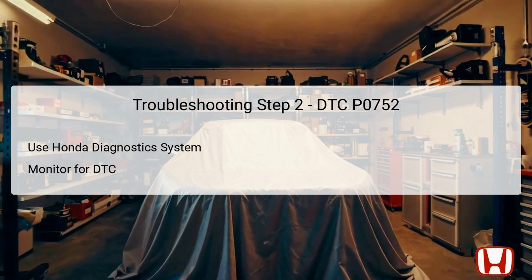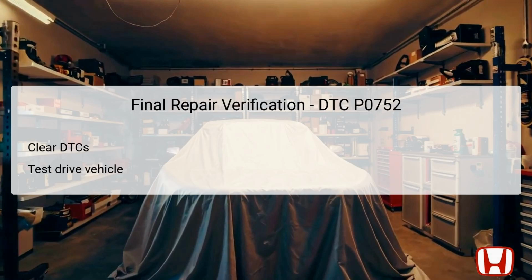Utilizing this tool allows for an in-depth analysis, ensuring that the technician can observe any pertinent fault codes directly related or complementary to the suspected malfunction. Clear and accurate readings from the HDS are important to determine the next course of action and to confirm the diagnosis effectively. Upon completing repairs associated with DTC P0752, it's important to perform a final verification step.